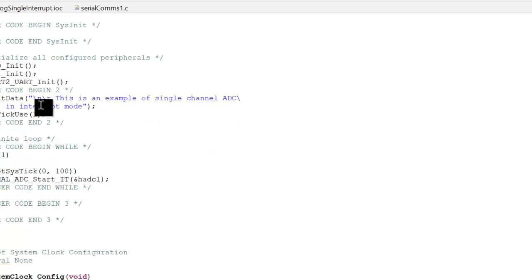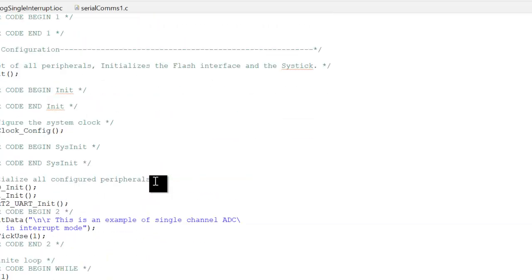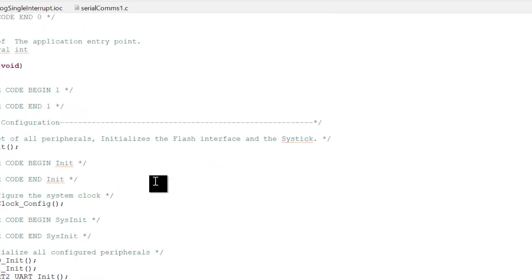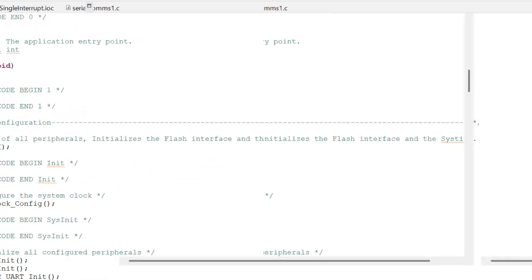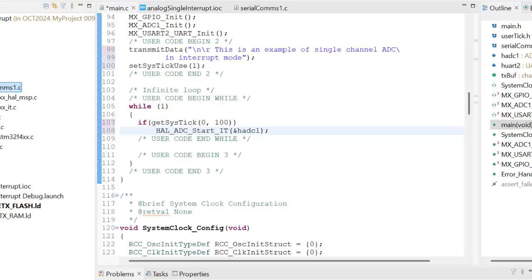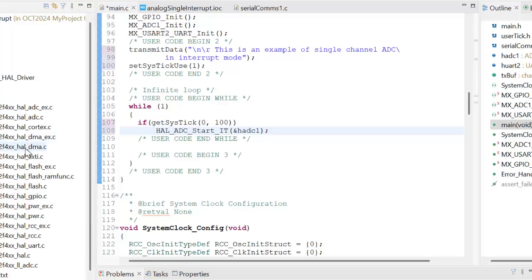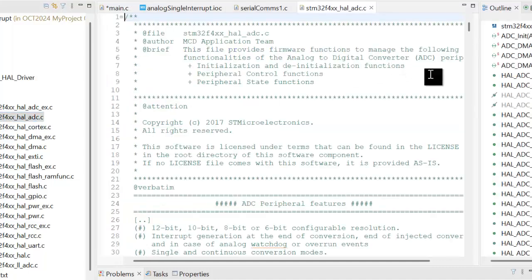Okay, right, that's all. If you remember when we talked about interrupts, once it is interrupted, we need the callback, or the interrupt service routine. There's already code for that to trigger the ADC. Then we go back to the driver, click HAL driver, click on source. From the list, click to open HAL ADC.